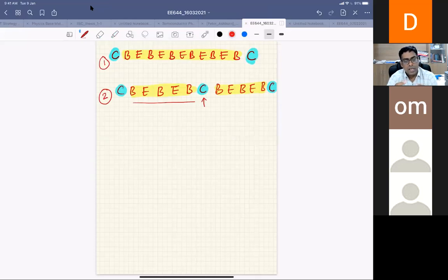So you see, when your transistor is conducting more current, your IBRB drop, your IR drop, will also be high. So the emitter crowding effect increases as you draw more and more current from a bipolar junction transistor. To avoid that, you have to make these emitter and base fingers, and keep those fingers very close to each other, so that your emitter crowding effect can be reduced.